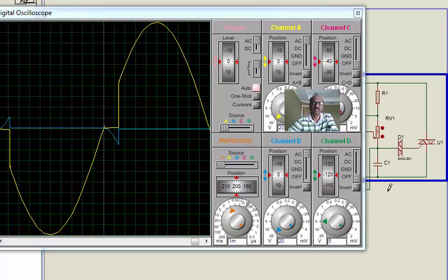And what we find is the diac is conducting at 33 volts. Now see, this is the 20 scale. What we have here is the 20 volt scale, and when it crosses 30 volts, it starts triggering. It starts conducting. At that point, the triac conducts, and in the process we get this waveform, a little cut from the 0.